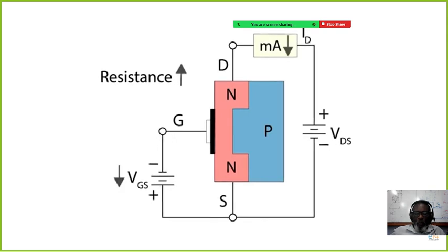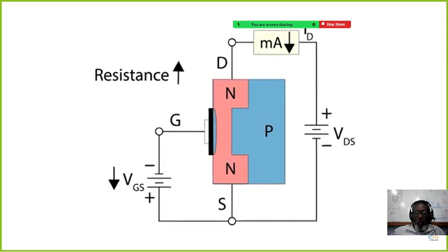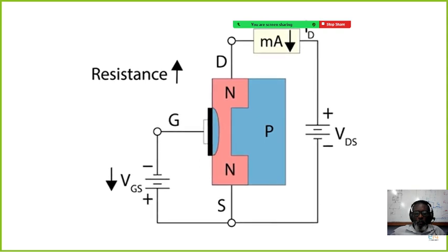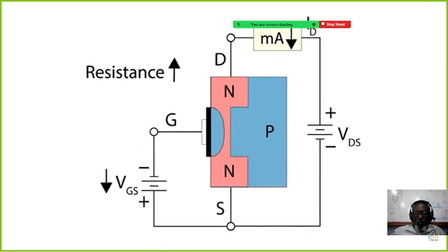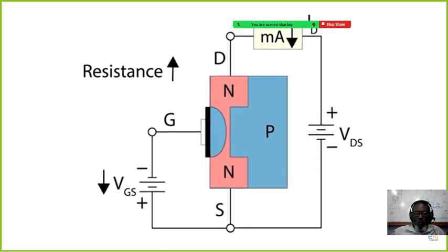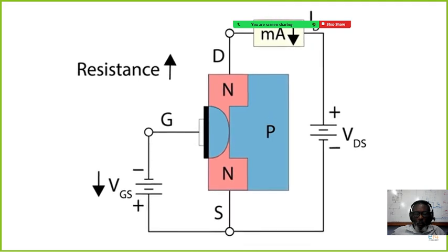When there is a voltage at the gate, and the gate is reverse biased, the DMOSFET is operating in depletion mode. It behaves like a JFET. As the bias at the gate grows stronger, the depletion zone also grows. Proportionally, the channel is narrowed, increasing the resistance and restricting the flow of current through the channel between the source and drain.